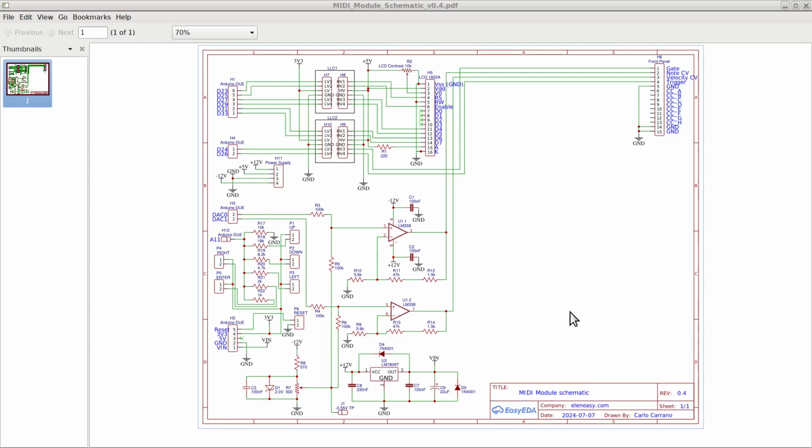Here you can see that I have eliminated the whole circuit for creating the trigger signal analogically from the gate signal. I also moved the connector toward the front panel from the center right of the picture to the upper right to make some space for the circuitry that we will design later on for the control change signals.